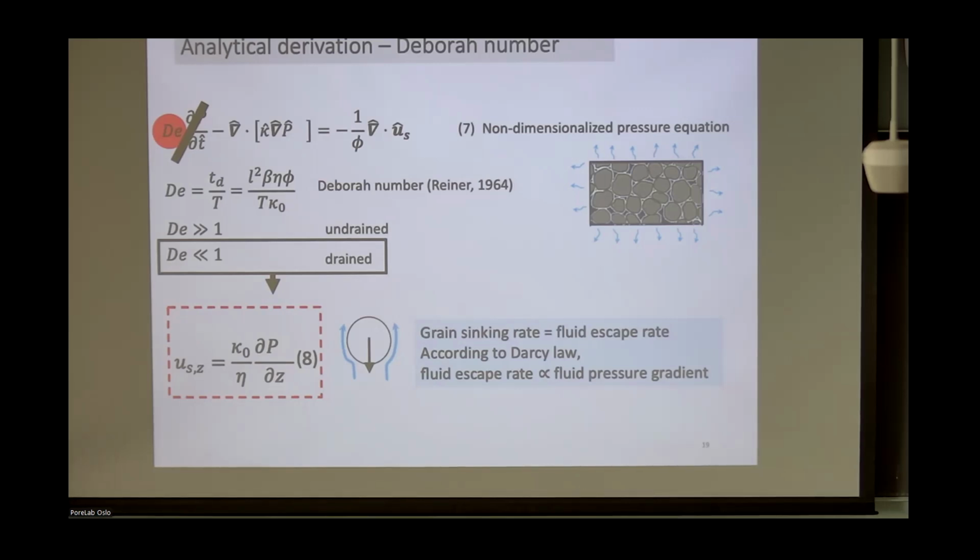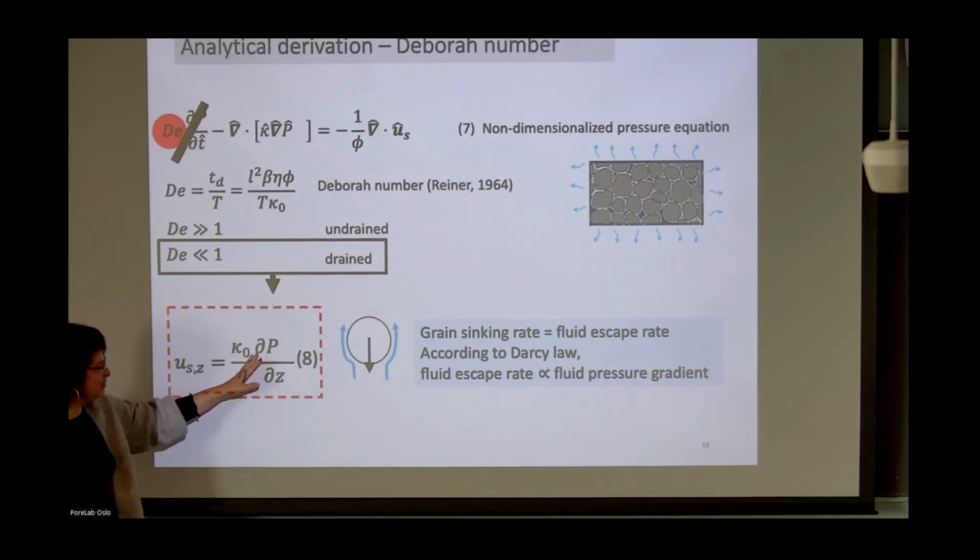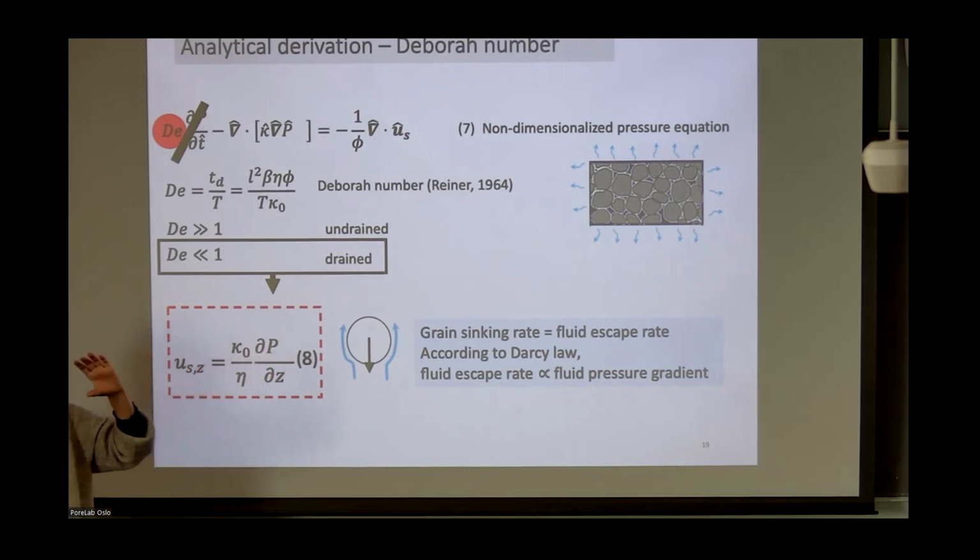So in your equation, it's basically assuming that there's no grain contact. So the solid velocity is set entirely by the liquid. Right. You'll see in a minute or two that there's a compaction front, and above it, everything is liquefied. The grains are falling basically together in a fluid that's going up because they have to. The fluid has to be exchanged with the grains as long as the grains are falling.